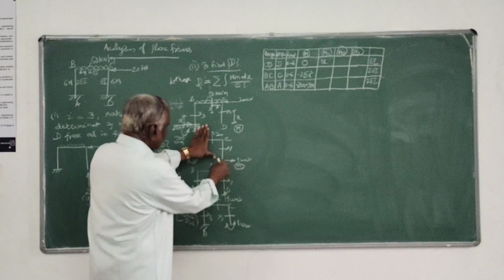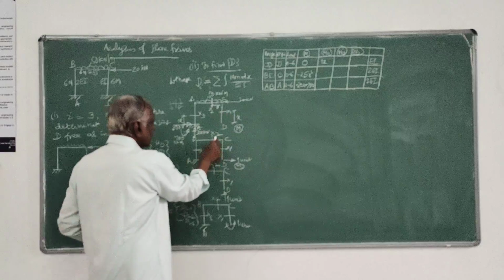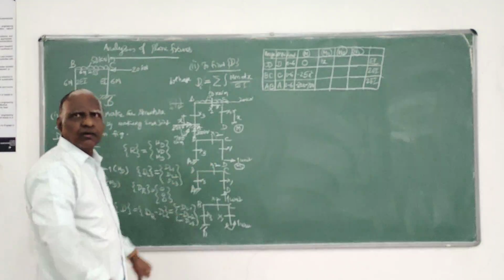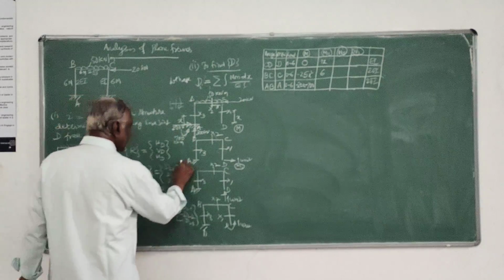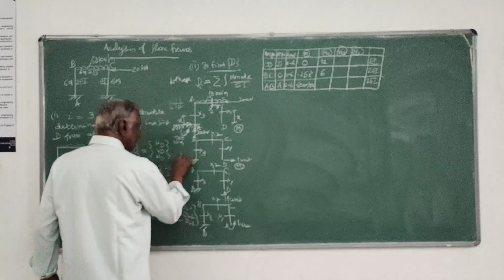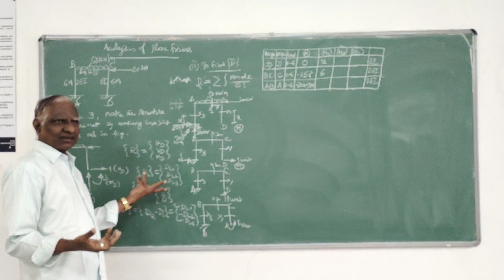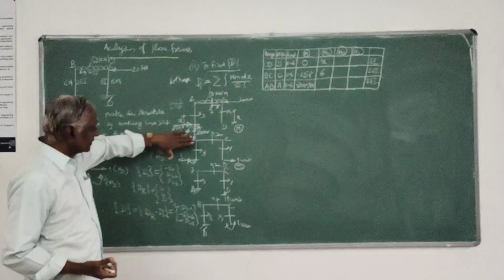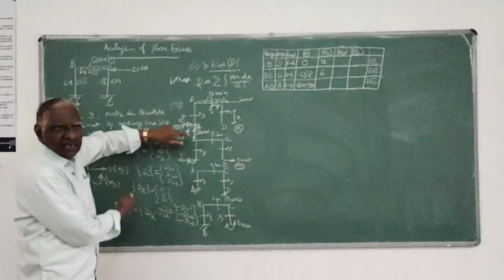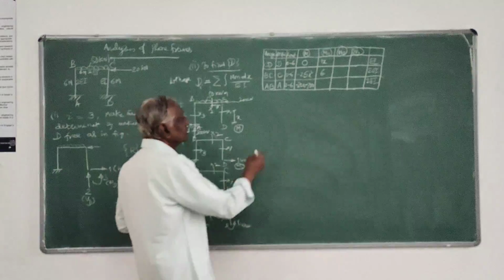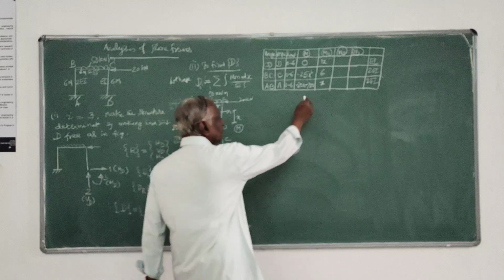Then about this section, it is 1 into this height 6, that also gives sagging type of moment, so it is plus 6. Now here there must be an equal and opposite reaction, sigma V equals 0 and sigma M will not give anything. Here it is 1 into x, again sagging because of inside tension. So these are the moments.